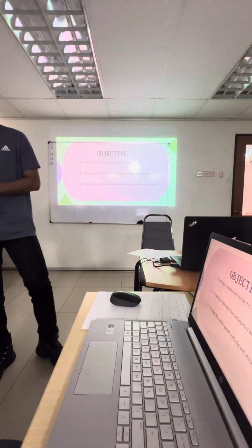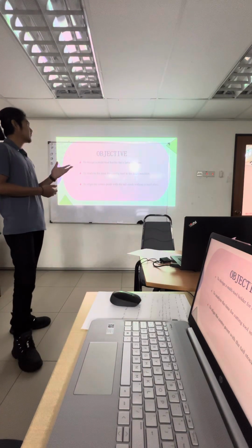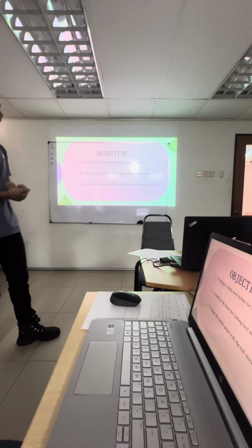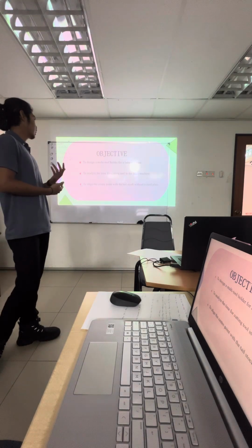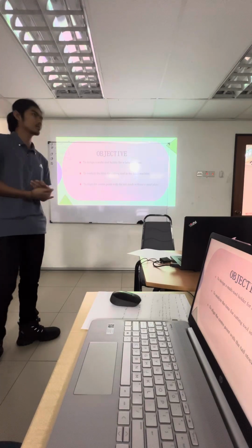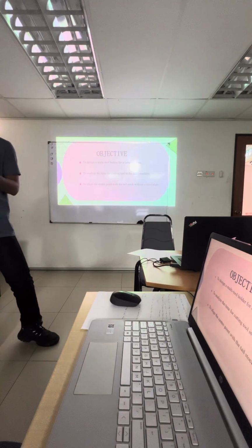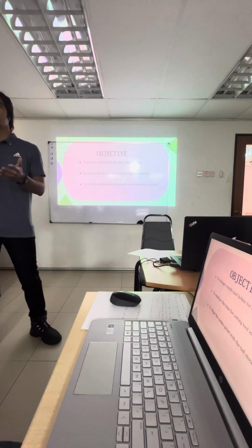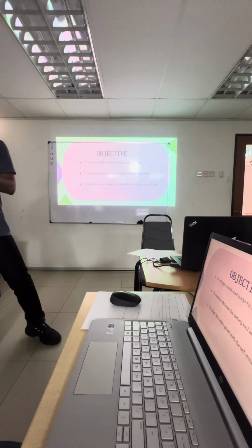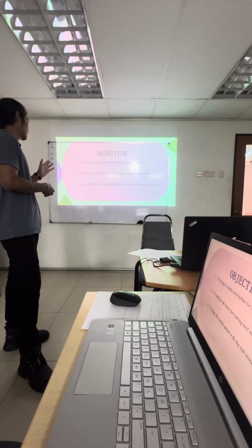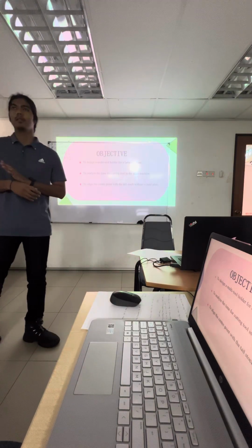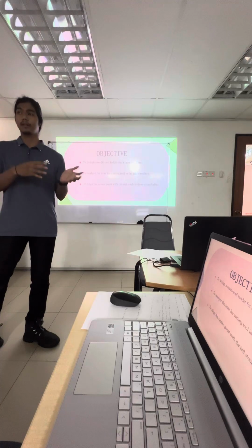For the objectives, our main objective is to design a multi-tool holder for the machine, improvising the existing tool post. The second objective is to analyze the time for changing the cutting tool in the lathe machine. Before this, we might spend around 5 to 10 minutes to change the cutting tool. Now with this product, we can reduce about 1 to 2 minutes, depending on individual skill. The last one is to align the center point with steel stock without a steel plate, so there's no need to compete or take turns with other students to use a parallel bar to set up the cutter at the machine.